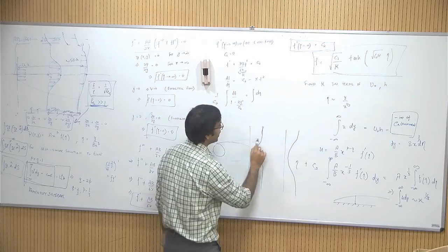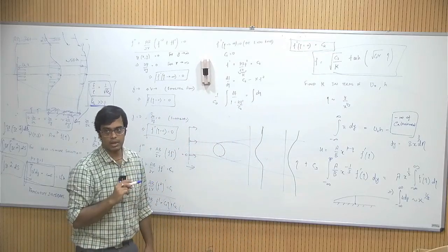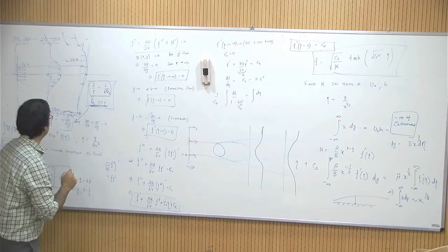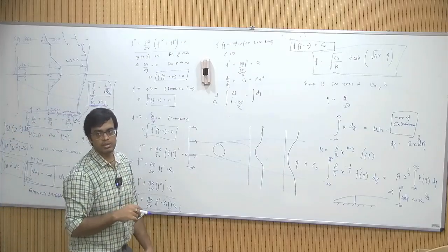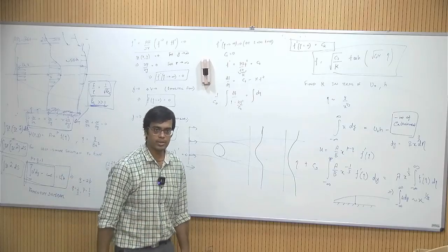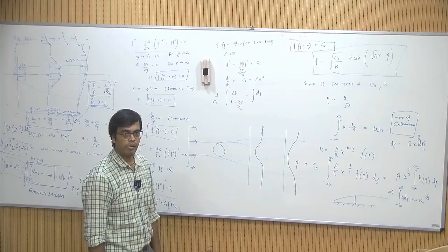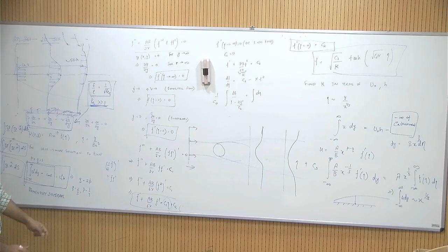You can apply the boundary layer theory in the wakes as well. You can reach the same equation, but this won't have self similarity. You will not be able to find a condition where self similarity can hold. You have to do the algebra and find a contradiction. As I said, self similarity is one indicator that we can maybe approach. I haven't found it in my practice.